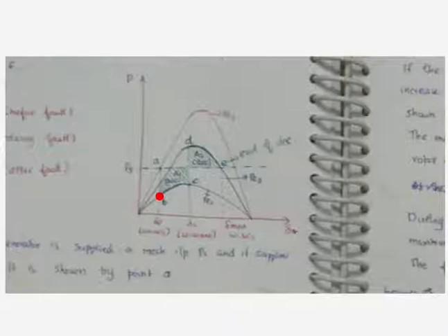And due to the fault, the effective electrical output also reduces because all the power does not go to the load, right? So this will cause the system to accelerate. And at point C, which is our critical clearing angle, we will clear the fault. When we remove the fault, the new network won't go back to the original curve because the new network does not have one line, so it will go for an intermediate electrical output characteristic and come to the point D.